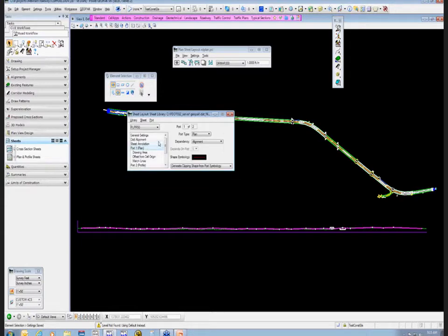All right. Ports. Ports are basically the view, or where we're going to clip and create that border. It's the view in which I need the boundary to be made. And we have basically 3 types of ports. We only use 2. We've got a plan port, which is going to show our plan view. We have profile ports, which we use when we're clipping our profiles because they're a little bit different. And then tabular data. We don't use those, and it's something that's been around for a long time, but it's not one that we use. So I'm going to skip that part.